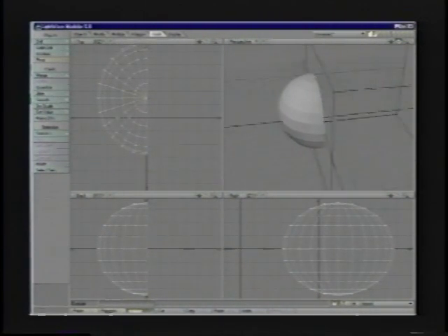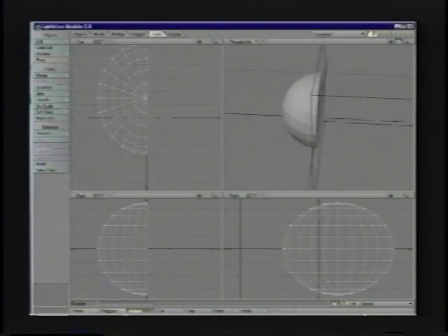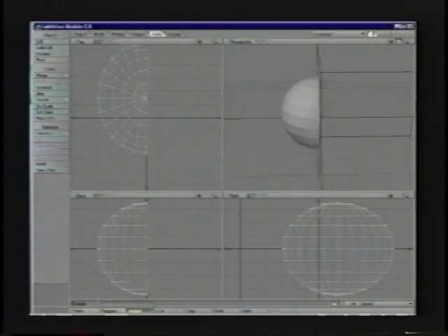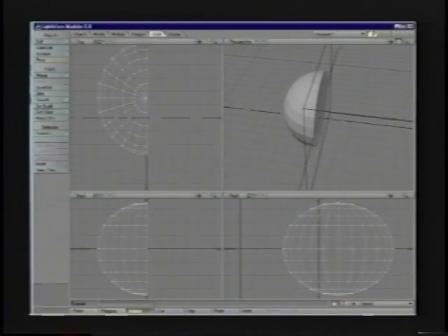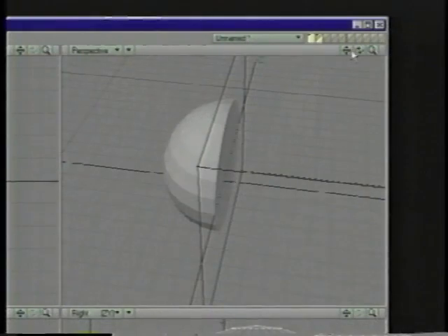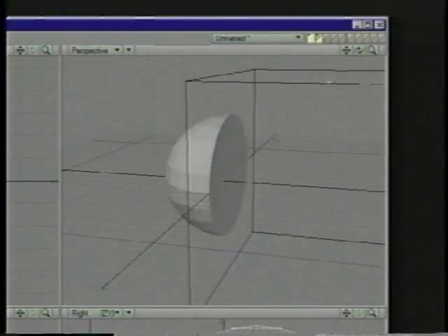And so that's a useful tool if you want to go in and cut chunks out of your geometry, and they can be any shape that you want them to be. I could have used a ball, a cylinder, or what have you as this shape, as my cutter shape, as it's called, instead of a box if I wanted to. We basically sliced this ball down the side and created geometry inside of it.